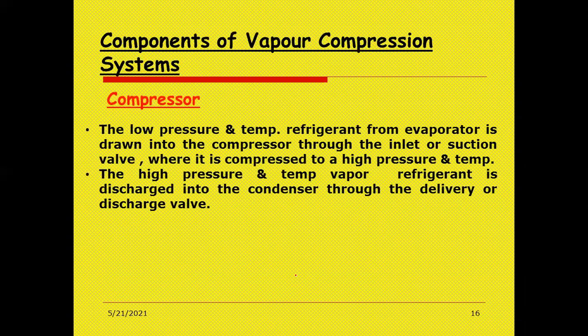Now the next topic to be discussed is the components of vapor compression system, right? We'll discuss the components of the vapor compression system, VCR. So if you see the compressor, the low pressure and temperature refrigerant from the evaporator is drawn into the compressor.